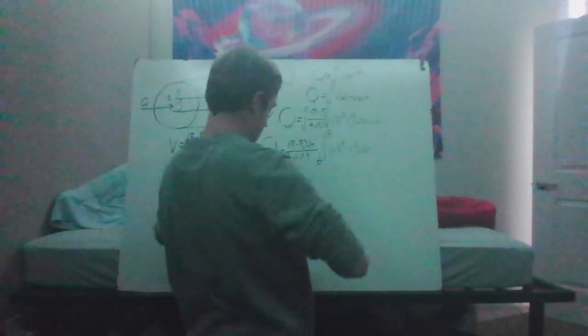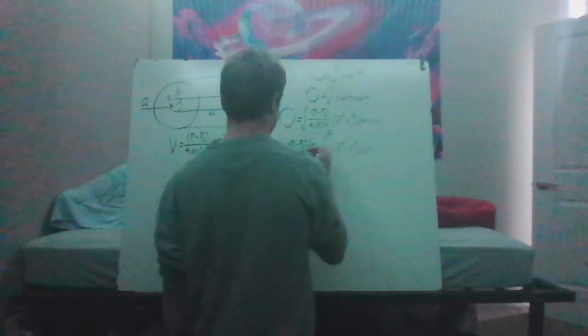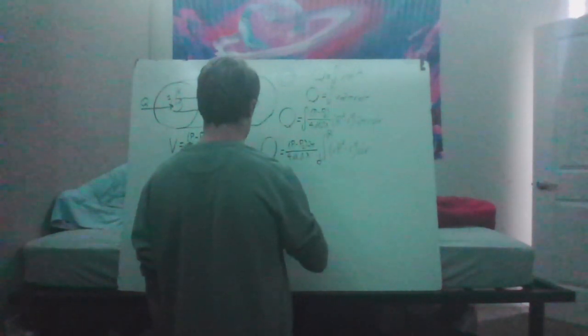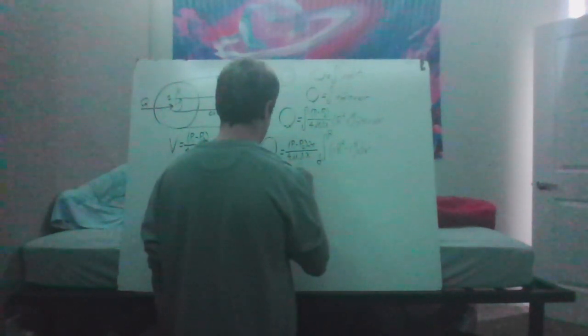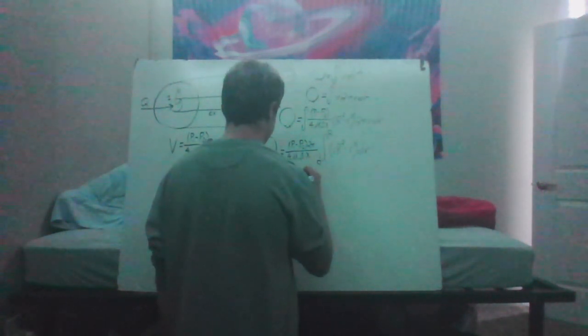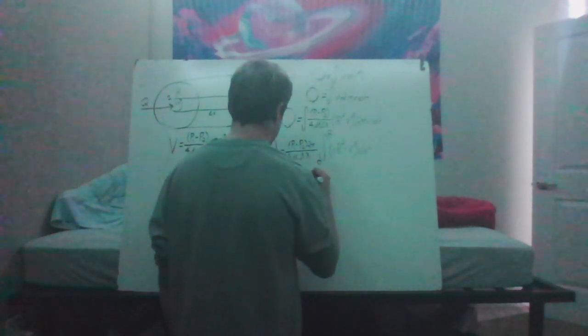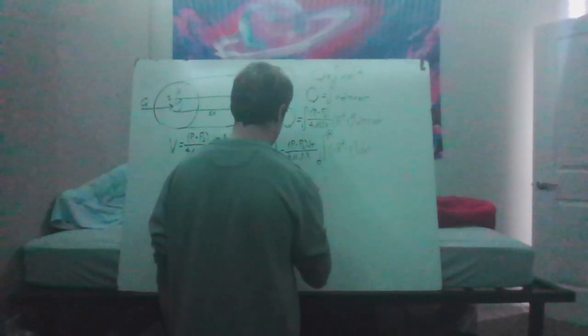So now to evaluate this integral, again our constants will stay the same, but I'm going to simplify this 2 over 4, which becomes 2 in the denominator. So we will have P1 minus P2 still, and then just a pi over 2 mu delta x.